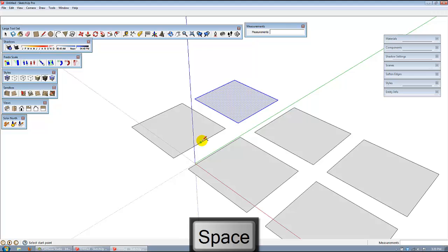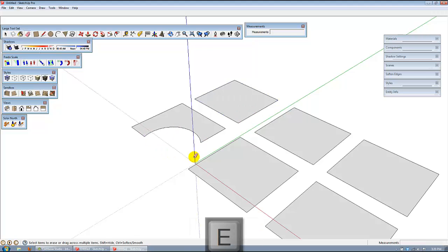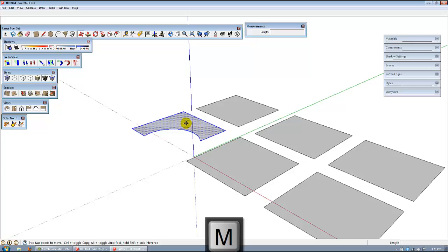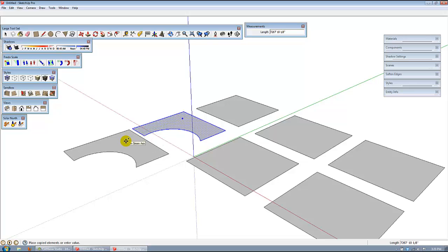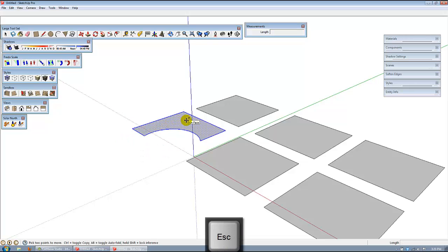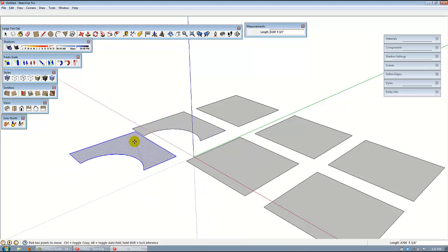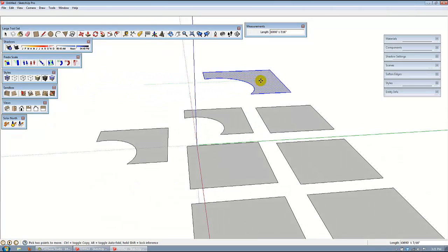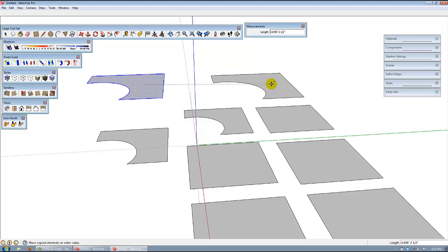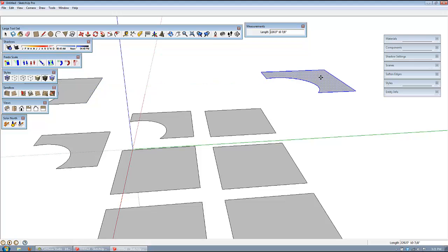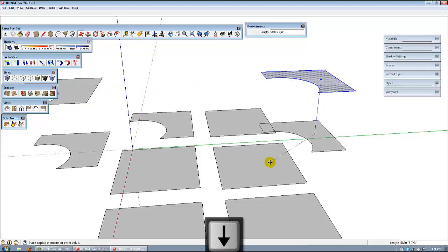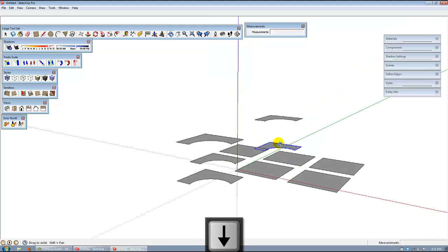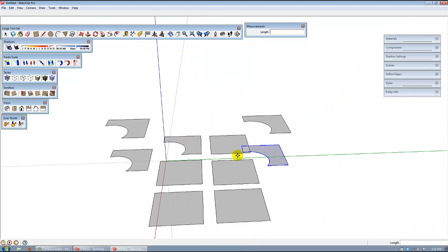And if I change the shape, and then move it, M is the keyboard shortcut for the move tool. So you want to get used to using your keyboard shortcuts. Control for the move copy, and we can move copies of that new shape now. And notice how when I move this shape, if I just hit Control during the move, it's saying, okay, you changed your mind, you want to move copy. Okay, we're moving a copy now. And I can inference to there, so you can do some really neat stuff with move copy.